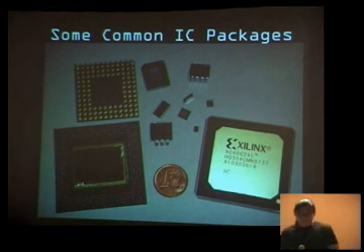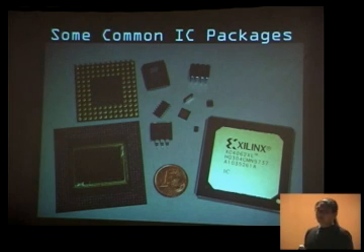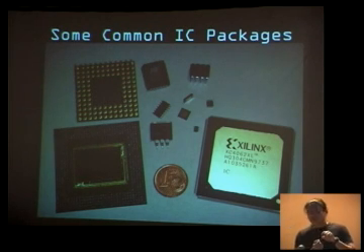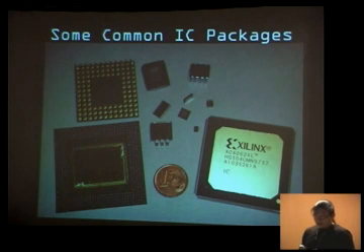Those guys actually have no leads on them whatsoever. So when you look at it on the board, you just see these little metal divots coming off on the side. And those, you got to be a little careful when you're trying to reverse those, because you got to look at the manufacturer's.